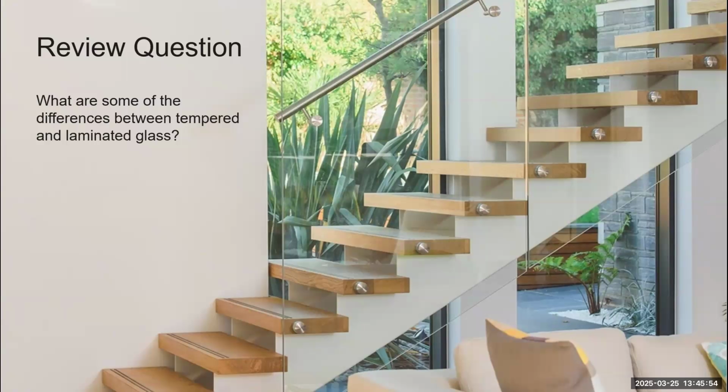The first is the overall wind, typically anywhere from 90 to 180 to 200 in hurricane. Then we have the overall installation above grade, from 0 to however high it goes. Then we have the overall exposure category, which is zone B, C, or D. Those are all the things we need to take into consideration.